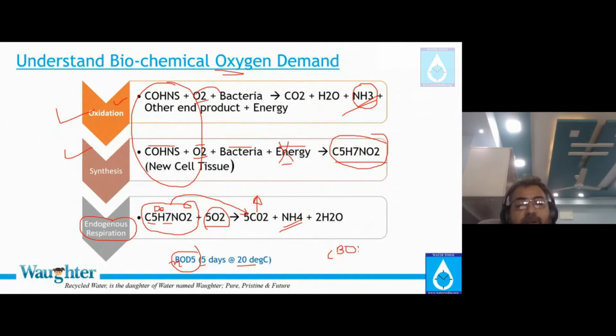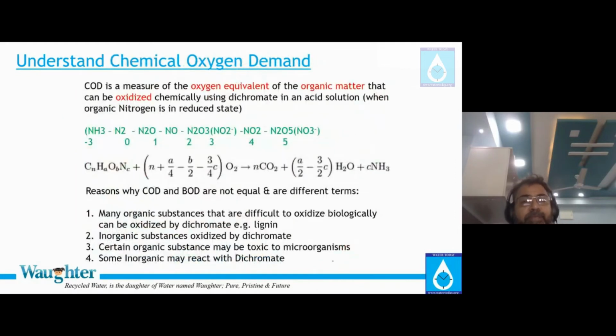And if you continue this experiment for 15 days, you can remove C and write NBOD, nitrogenous BOD. That means BOD measurement for full nitrification for 15 days. Even you can calculate the air requirement by NBOD numbers from the laboratories.